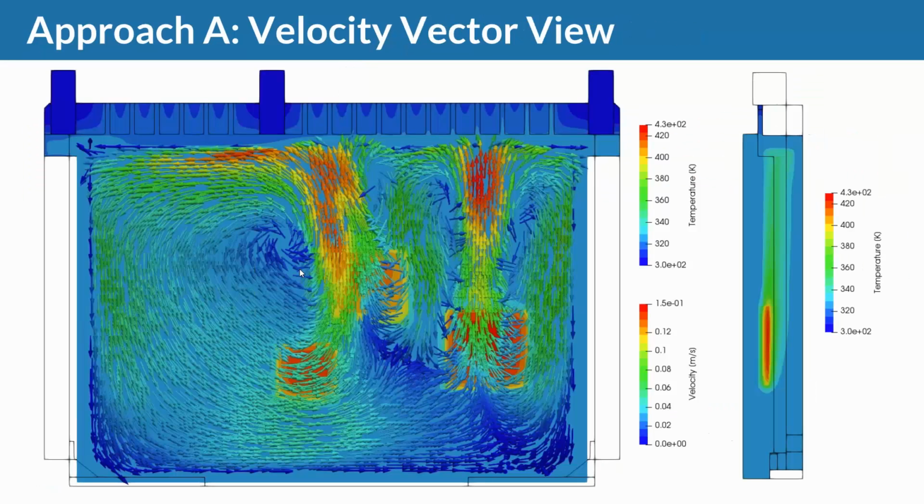So the important information here is that it's basically two things we're looking at. The first one, the chips are too hot, right? We're looking at 90 degrees Celsius max temperature, and we're significantly beyond that, somewhere at 150, something like that. So it's too high. The second thing is that our chip 1, the one here in the lower right, is the one that gets the hottest. And it might be due to the fact that convection here is not as effective, right? Because I don't have this big vortex structure. I don't have this big area where air can be cooled down again.